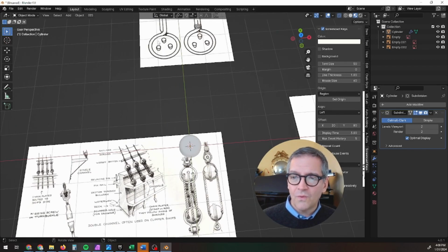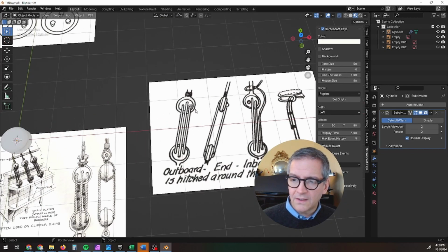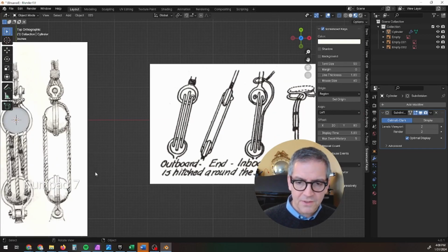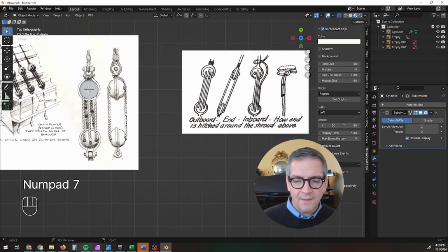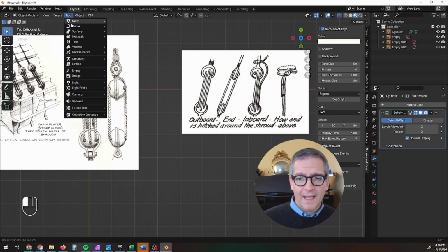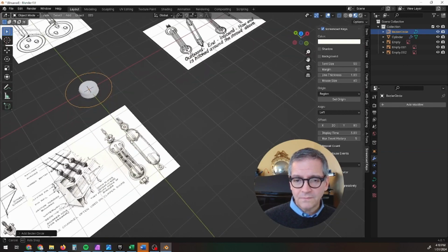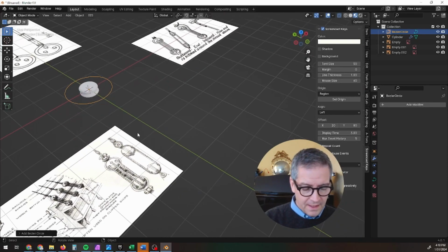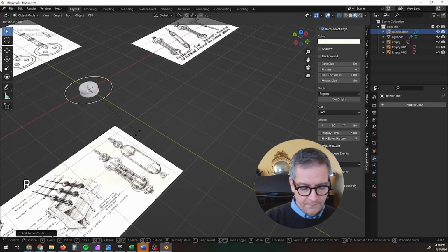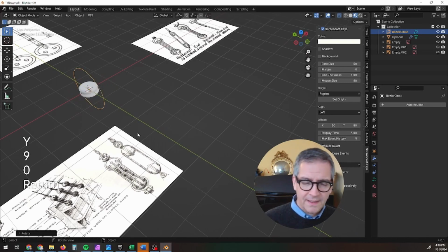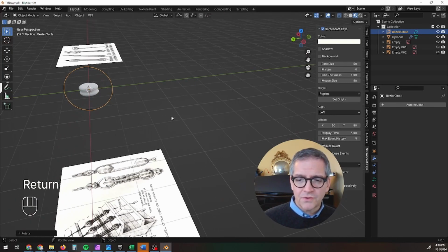Now here you can see they're more evenly spaced inside. Again, here you can see they're more evenly spaced. This is Jack Coggins's sort of understanding of their shape. I'm going to move them slightly. I'm going to make them more evenly spaced inside here. So how do we do this? Again, we're going to use a Boolean. So what I'm going to do is add a curved circle. Okay, I'm going to rotate it 90 degrees, RY90, to make it that. Then I'm going to shrink it.